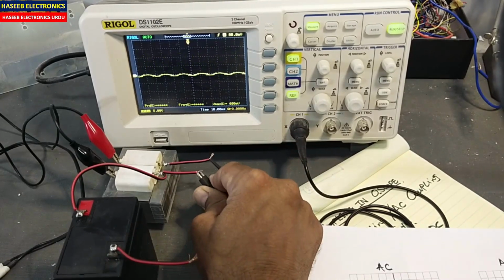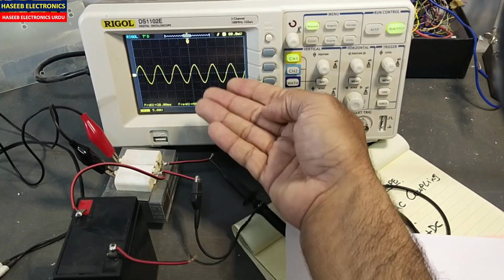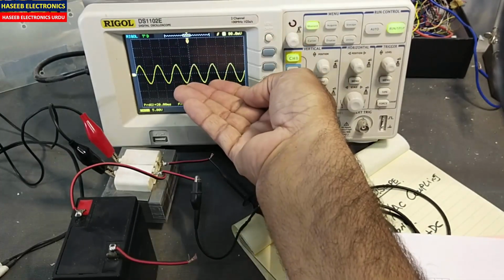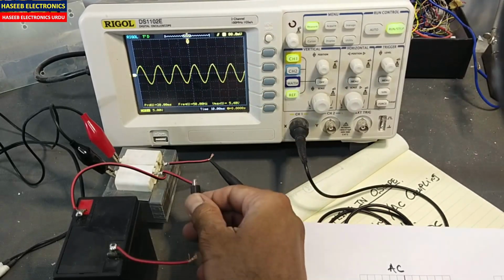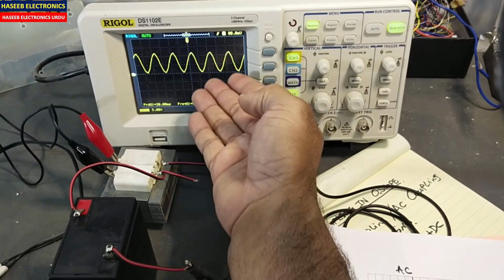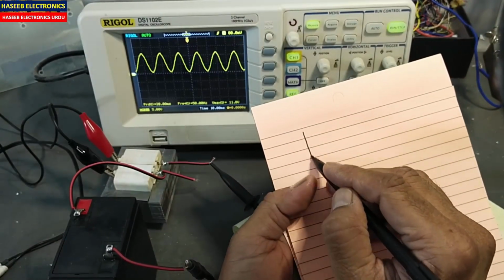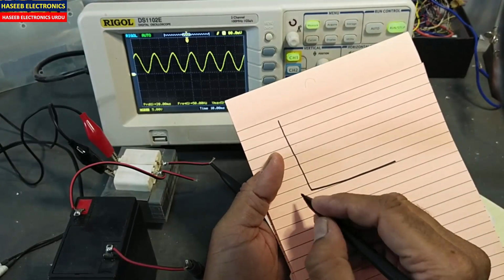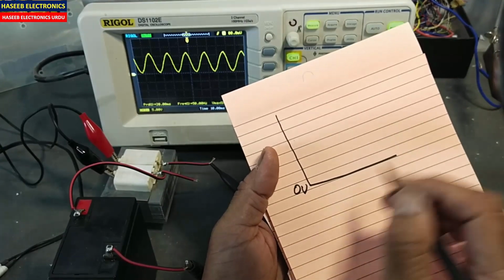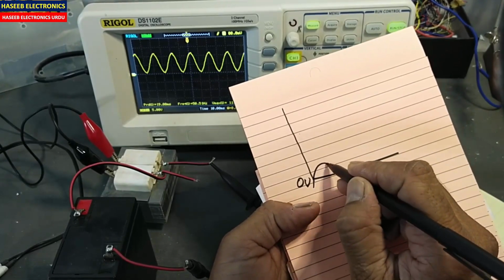Our pure signal, that is a sine signal, comes at zero, half cycle on the upside, half cycle on the low side. But here this signal is now elevated. If you see closely, this is 0 volt. When we tested the AC signal, it was showing here.